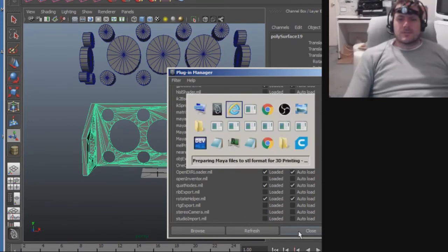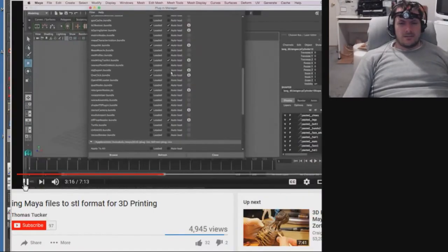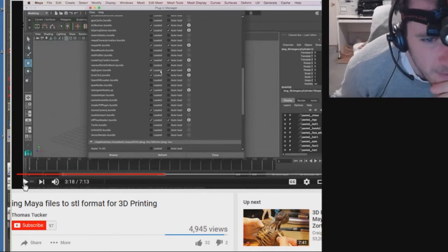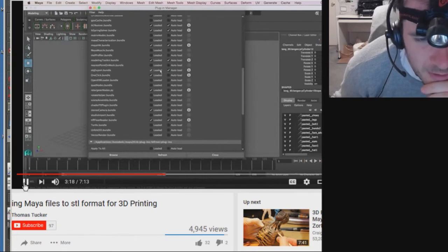Okay, so it was different than what he had. His said obj export .bundle. Oh, it's just a different file extension. His is .bundle, mine's .mll. It's still obj export. Make sure your OBJ export bundle is set up, or this will not work whatsoever.